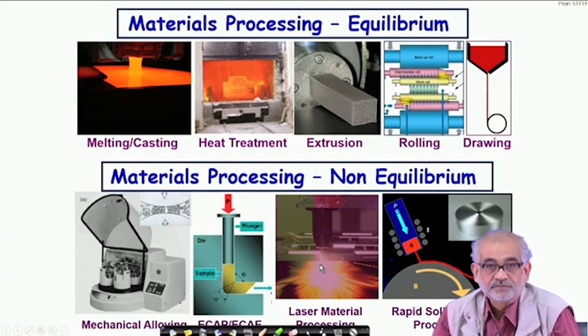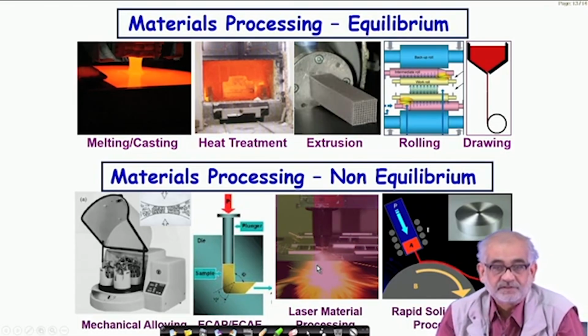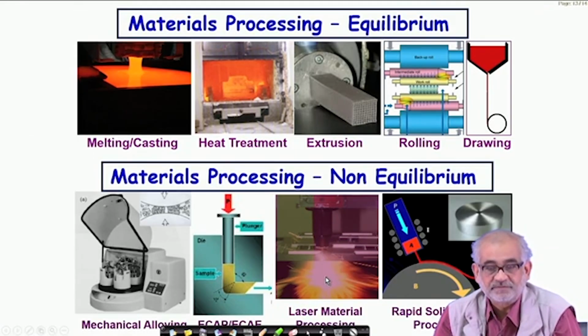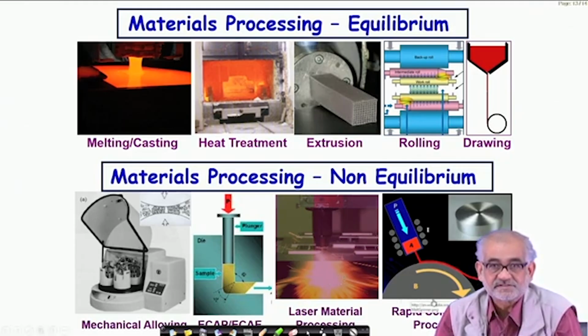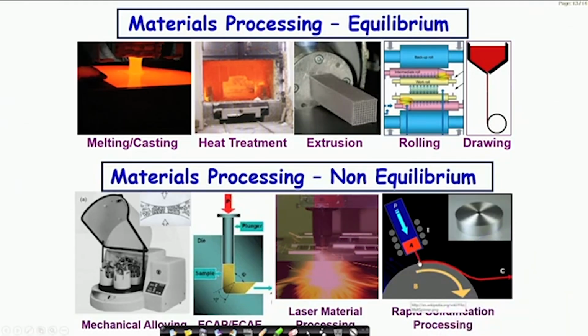We can do melting of a very small volume using a laser beam, and under the beam we can instantly take a solid in the form of either bulk solid or powders or wires into the liquid state and then subsequently quench them by self-quenching and create certain solid objects, from small and gradually built into a bigger one through an additive process. We can solidify a liquid onto a wheel rotating at a certain RPM, but most importantly the wheel is made up of high conducting materials like copper, which allows very fast cooling.